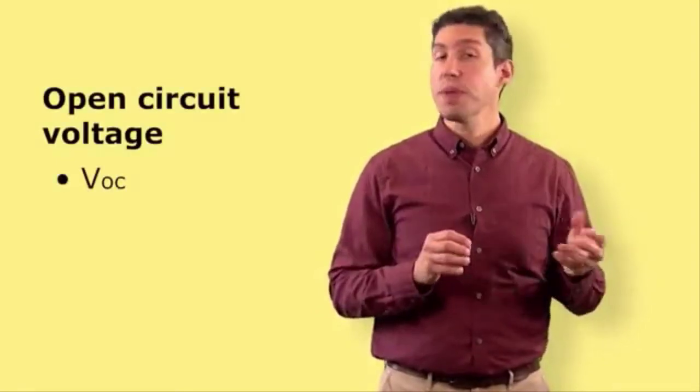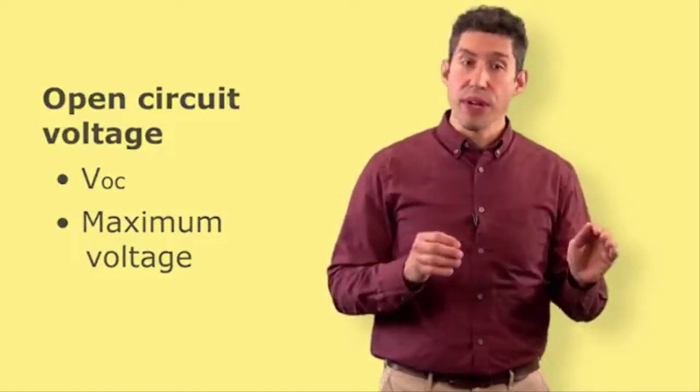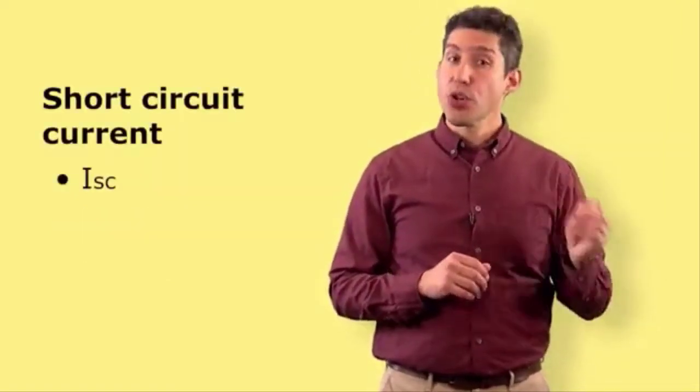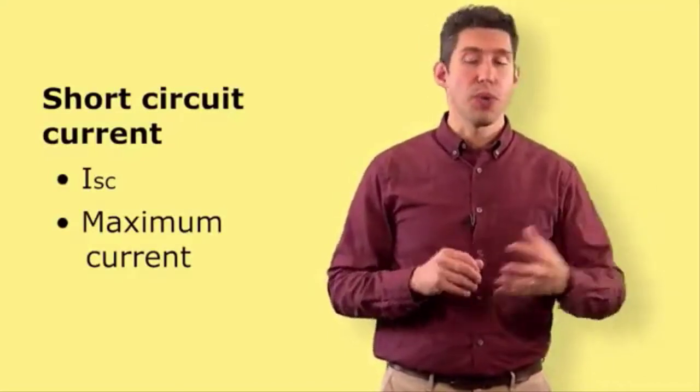The other 2 key terms are the VOC, or open circuit voltage, which is the maximum voltage that the cell will ever put out, and the ISC, or short circuit current, which is the maximum current the cell will ever put out, or the module will ever put out. We'll look at these 2 terms more in another segment.